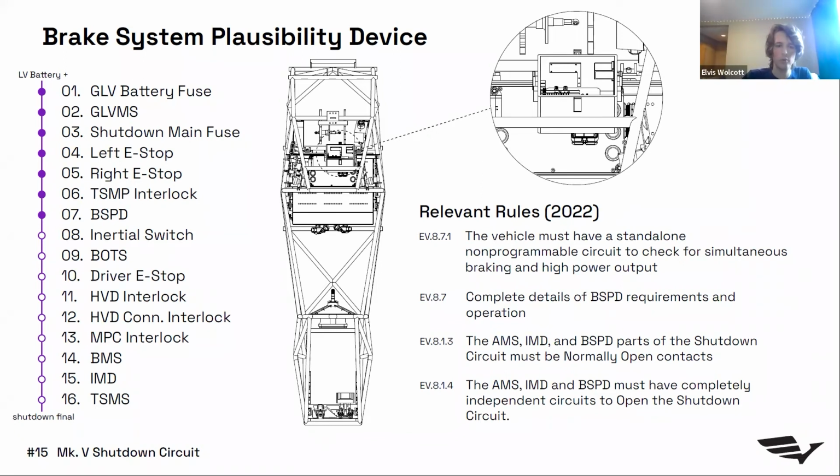And that's where the rules do allow. If you look at the schematic, there's a timing circuit built in that allows you to wait up to half a second before you actually recognize the fault, which gives you a little bit of wiggle room for sensor lag or parasitic capacitance or anything that could make it say something's going wrong even though it's not quite. It's also convenient because that little bit of time means that in theory the passive discharge circuitry should mean that our bus voltage is already dropping to a safe point by the time the BSPD is faulting and we're opening everything up and panicking.